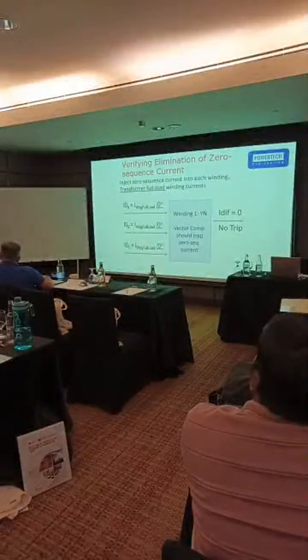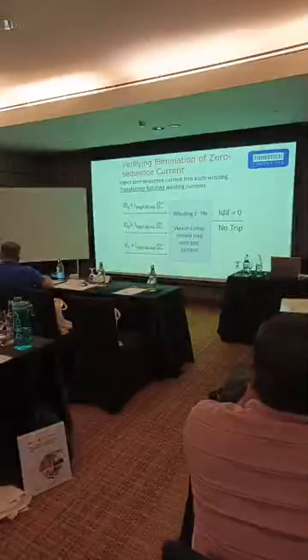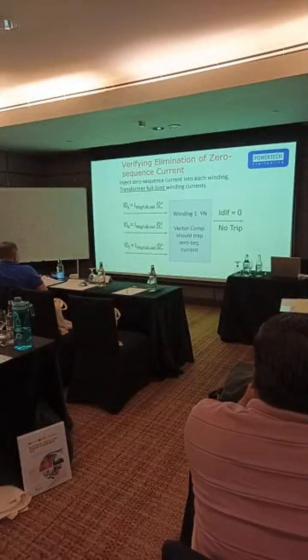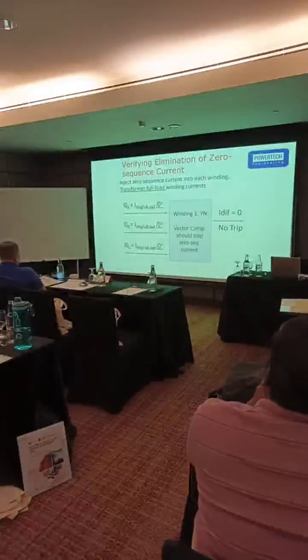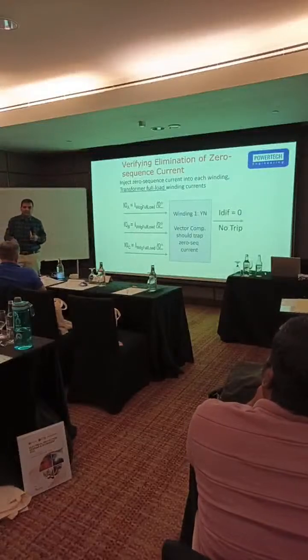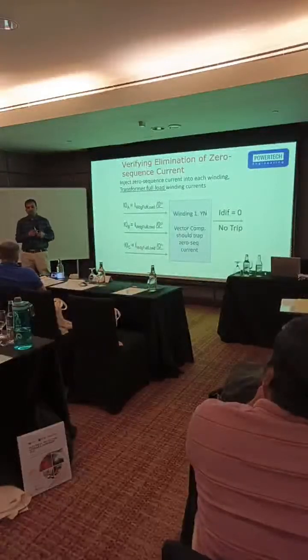This will work only when we are injecting a three-phase balanced current, 0, 240, 120. Symmetric current we are injecting. Suppose we are injecting a single phase current, then this current may be anything. There are four possibilities. I will explain in the coming slide. The single phase pickup current will be different than the three phase pickup current because of this internal compensation.